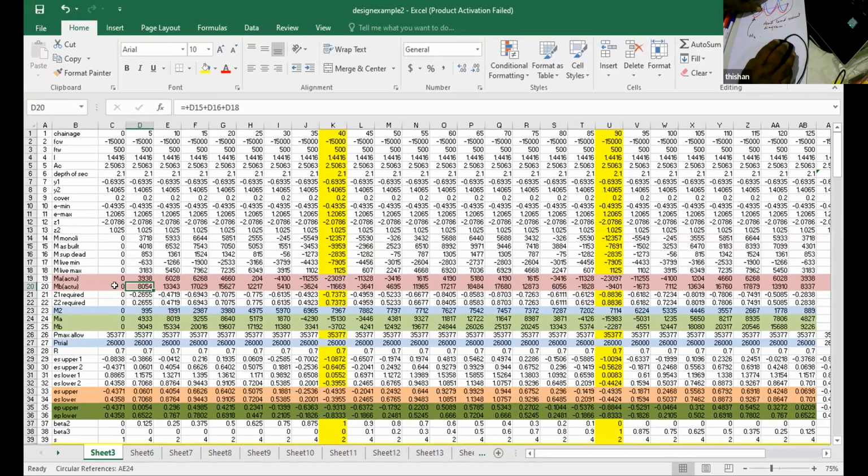I cannot be specifying the secondary moment based on both. So I have selected the secondary moment based on which one? Dead load moment diagram, as-built or monolithic. I think I have considered it based on as-built. Why? As-built is the one that is applicable immediately after construction.